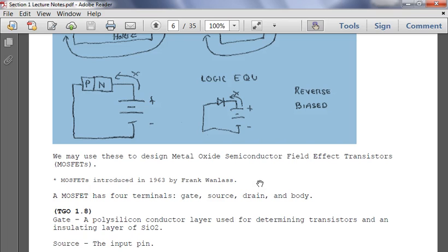And to be a little more clear on stick diagrams, this is one of the things that I feel is important to teach in this class because I want to teach you good design principles. Stick diagrams are very, very useful if you design a good stick diagram before you actually put anything into the computer, before you actually lay out the circuit. If you have a stick diagram, you may have to force yourself to follow design rules to make it work, but there's an algorithm to do that too. But you'll have the actual physical layout so you know the steps that you need to follow. So it'll save you a ton of time in actual design.